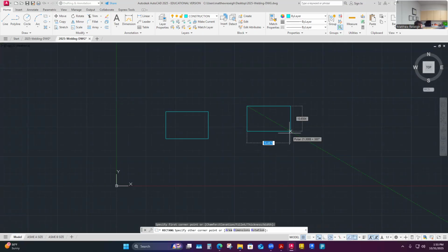How you get back and forth between those dialog boxes is you tab. So if I want to enter the width of this rectangle, I could enter it, and if I want to, and not hit enter, hit tab moves me to the other dialog box. There might be another key on the keyboard. I just use tab, that's the key I use. There's probably three other keys that will get you to that dialog box, but I use tab. I'm sure there's others, but this is how I go back and forth and enter this data accurately.